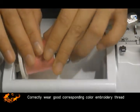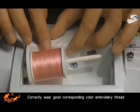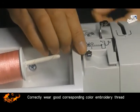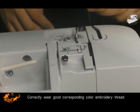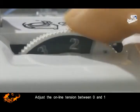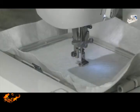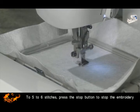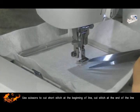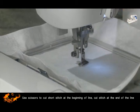Correctly thread the corresponding color of embroidery thread. Adjust the line tension between 0 and 1. Press the Start button to start the embroidery. After 5 to 6 stitches, press the Stop button to stop the embroidery. Use scissors to cut the short stitches at the beginning of the line. Cut the stitches at the end of the line.